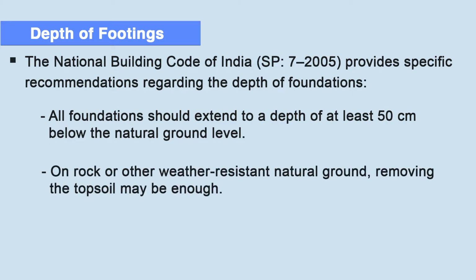On rock or other weather resistant natural ground, removing the topsoil may be enough. If the subsoil conditions adjacent to the construction site impair the stability of the building, the foundations should extend beyond these detrimental influences or be shielded from them through appropriate measures.